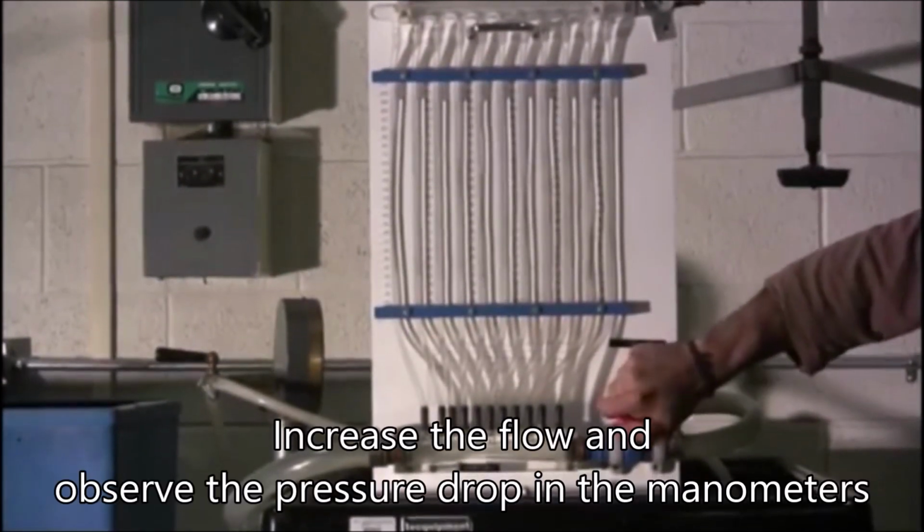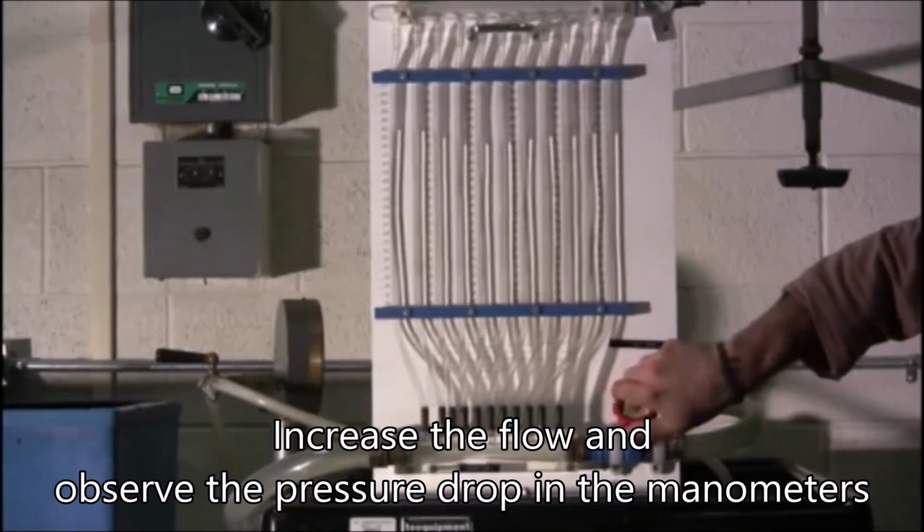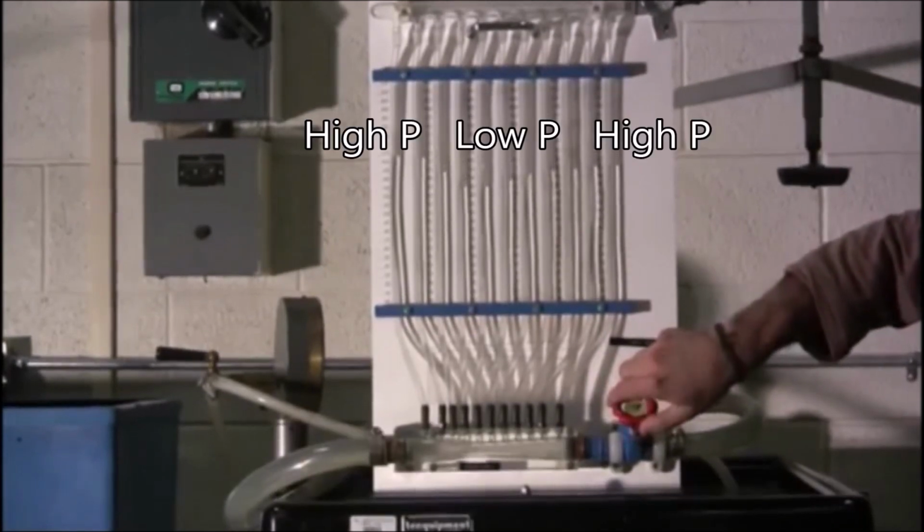Check that the Venturi device is operational by increasing the flow and observe the pressure drop in the manometers. The pressure drop should look like the following.